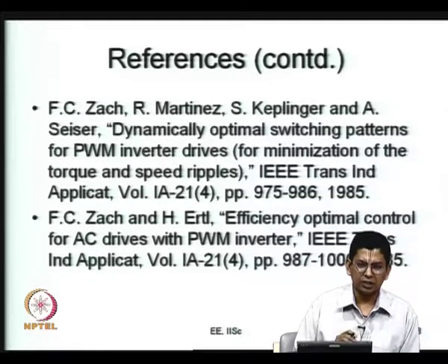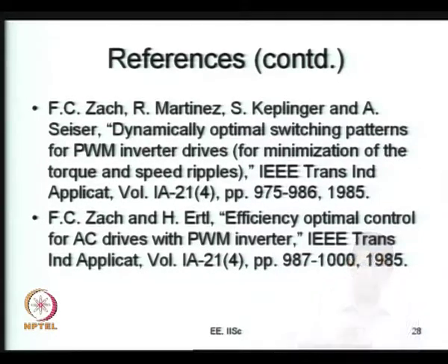This is perhaps the last lecture that we will have on low frequency PWM methods. In the low frequency case, we took it up essentially to get an essence of how fundamental voltage and harmonic voltages are affected by switching angles and so on. Now, we are practically done with the low frequency methods, and generally we dealt with selective harmonic elimination and optimal PWM, where you save them as a PWM waveform.